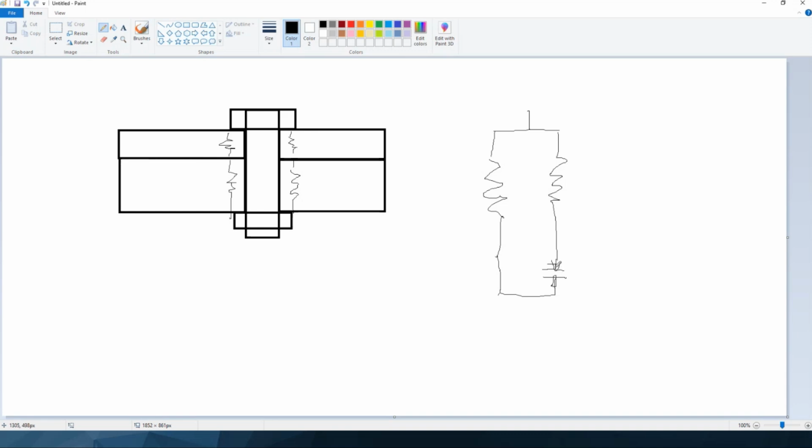That distance there is effectively how many turns I tighten it times the pitch of the thread. So that's the amount of material I'm effectively removing from that section by tightening this. So what I'll then end up with, if I pull them together and then lock them in place, is a tensile load going through this and a compressive load going through that. And the total load of those are the same. Does that still make sense?